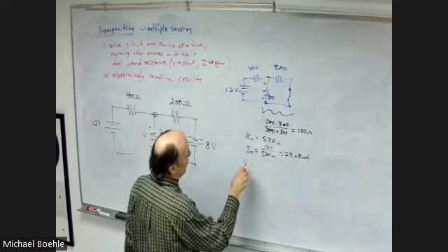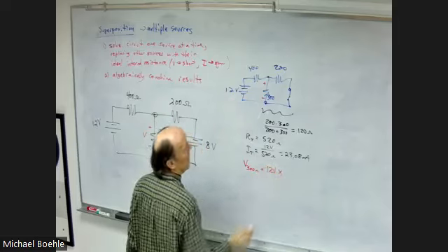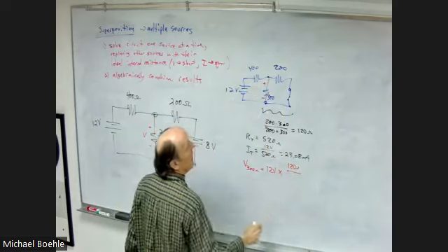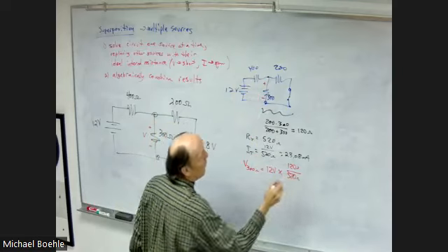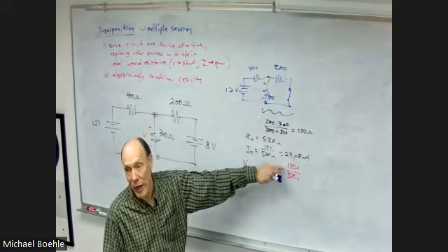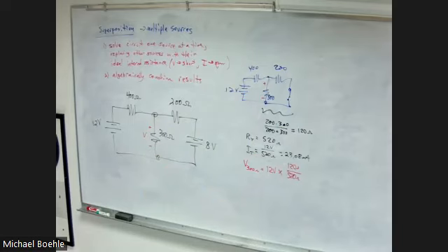So the voltage across the 300 ohm resistor will be the 12 volts being divided times 120 ohms, divided by the total resistance dividing it, which is 520. So that's my voltage divider formula. I could have just taken the 23.08 milliamps and multiplied it by 120, because that came from 12 divided. This is where, with series parallel circuits in general, there are multiple ways to get there. So whichever one works for you is fine. But either way, this ends up being 2.769 volts.